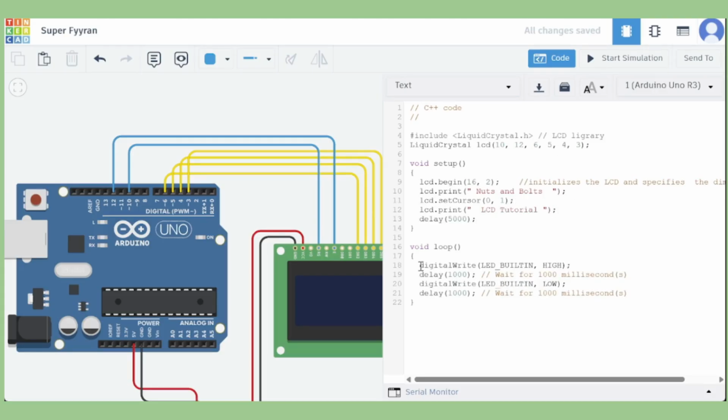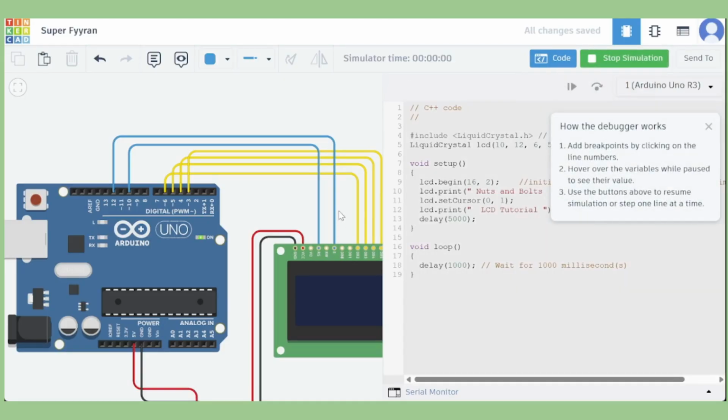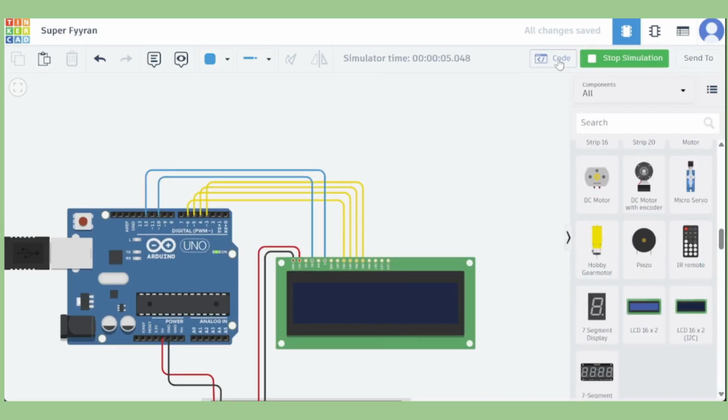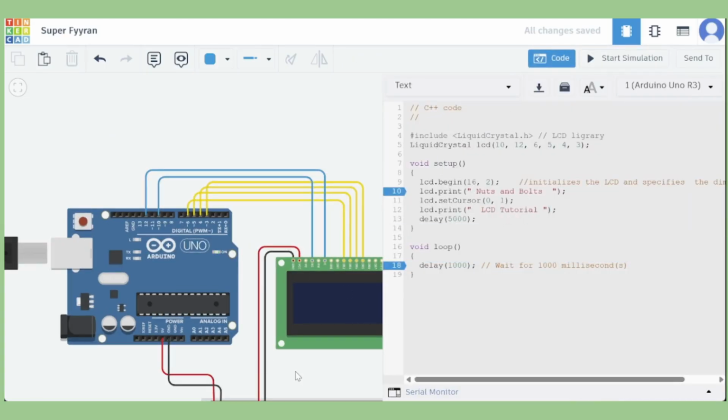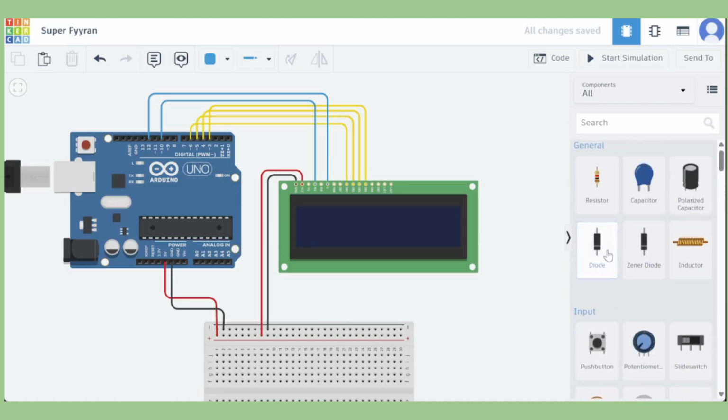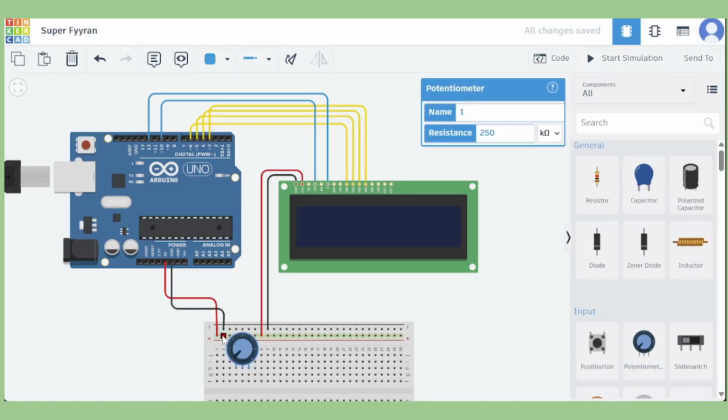After startup, the LCD is initialized. Based on my current Arduino D-pin connections, I used D3, D4, D5, D6, D10, and D12. It displays 2 lines of text, waits for 5 seconds, and then does nothing else. In the test results, the LCD didn't display anything.